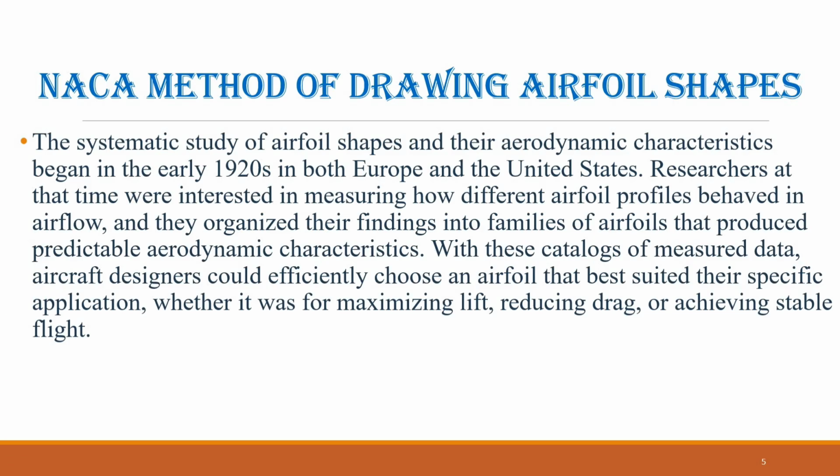These 00 series airfoils were symmetric, meaning their upper and lower surfaces were mirror images, and their geometry could be described mathematically, making them ideal for systematic analysis and design. By establishing a method to generate airfoil shapes mathematically, NACA not only made it easier for engineers to select airfoils for specific aerodynamic requirements, but also provided a foundation for further innovation in airfoil design that continues to influence aircraft and UAV development today.